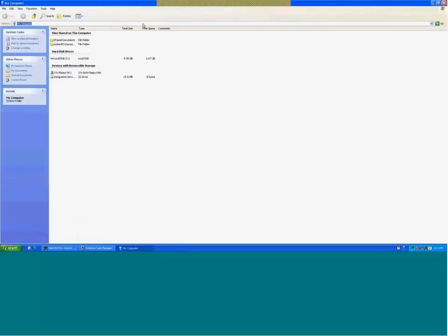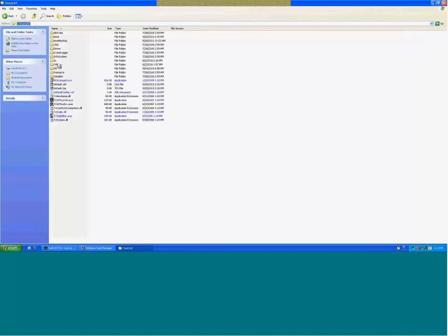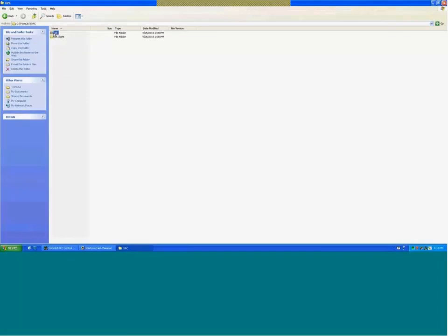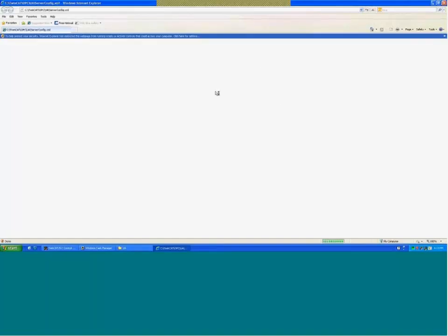When you install TwinCAT, you're going to have a folder called OPC. You go to UA, and you configure this XML file here. And that's again for TwinCAT 2. In this XML file, you're going to have all the information that you may need.